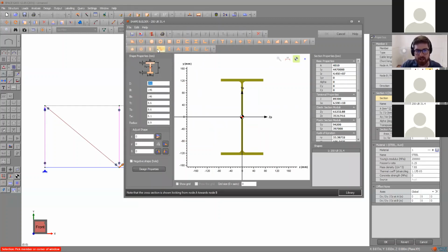That allows you to create your own custom section, which comes up much more often than you think. The standard shapes correspond to your standard thin-walled steel shapes or your standard concrete shapes. So you have like box girder, which you might use for, say, a concrete design, hollow sections, which you could use for a concrete or steel design, say a concrete column with a surface penetration running through it. And then you've got your sort of cold form steel sections for roof purlins or lightweight structural elements, which are your Z shapes, your C shapes, and your hat shapes. So you can build pretty much any section you want parametrically, and you can also build it up as a compound section.